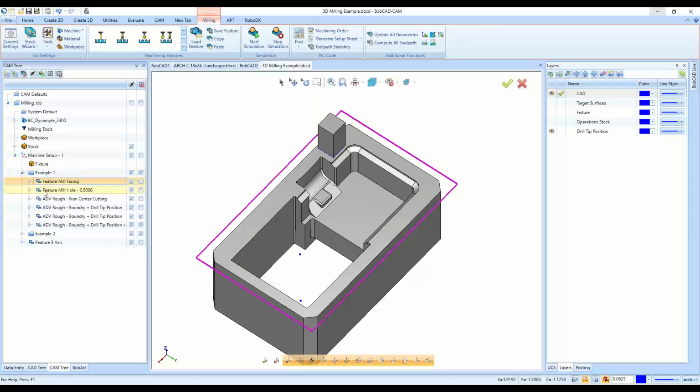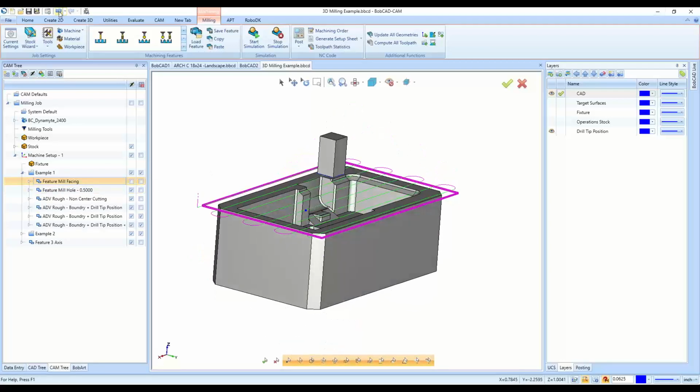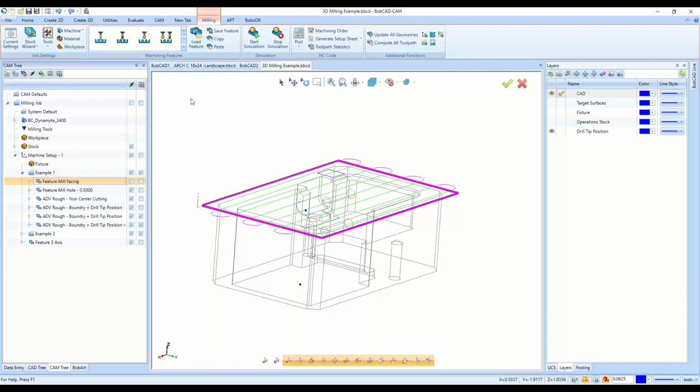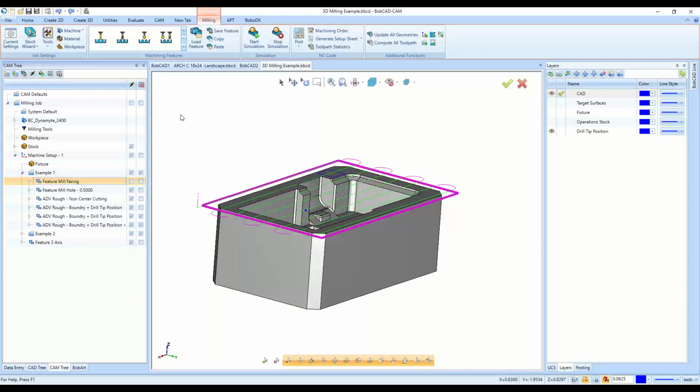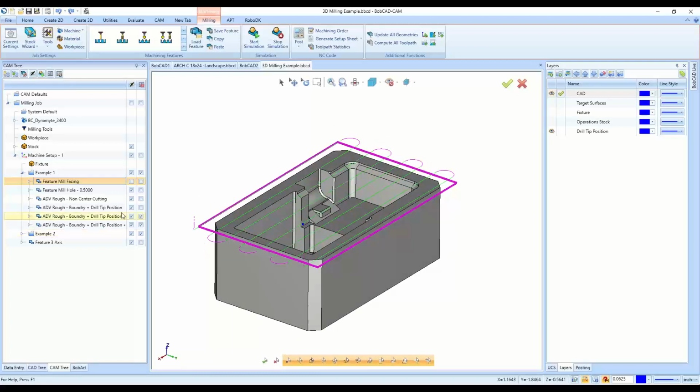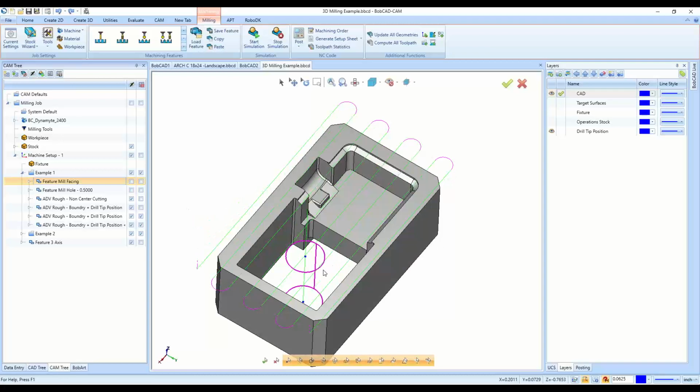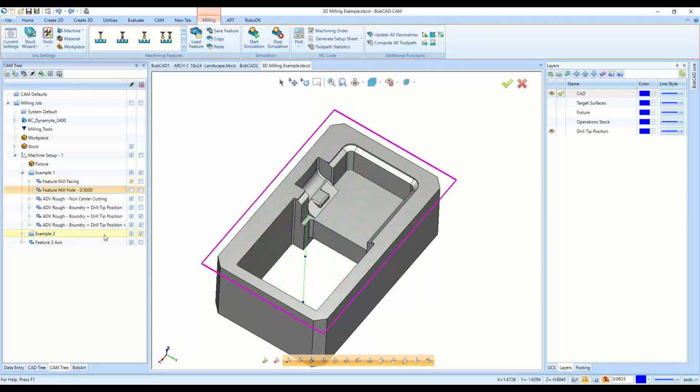Start with the facing operation. Instead of separating all of these out, well, here now that I've got a facing operation, I'll get rid of this boss. There we go. So now we've got the facing operation, we've got the drilling operation, and again, if you don't want to do all of these features separately, I guess what I'm referring to really is the drilling operation.